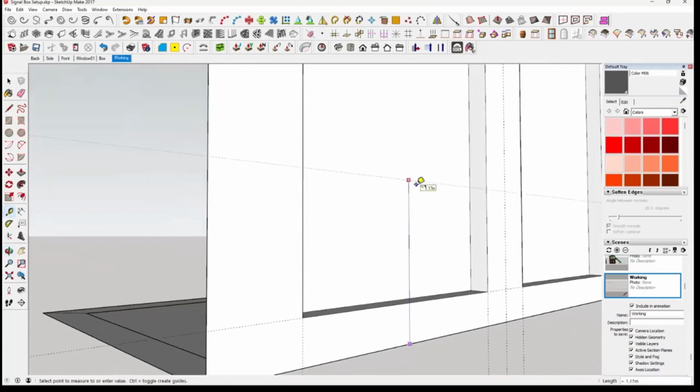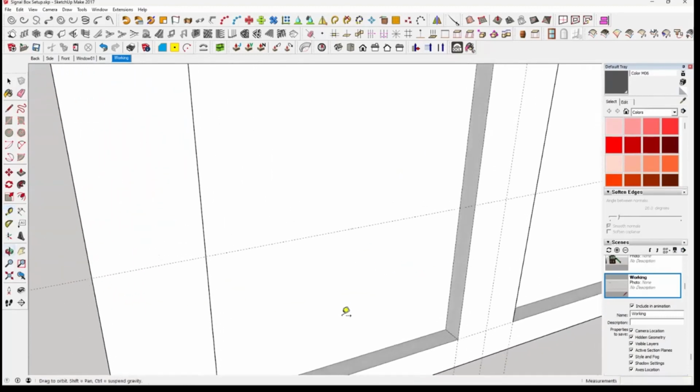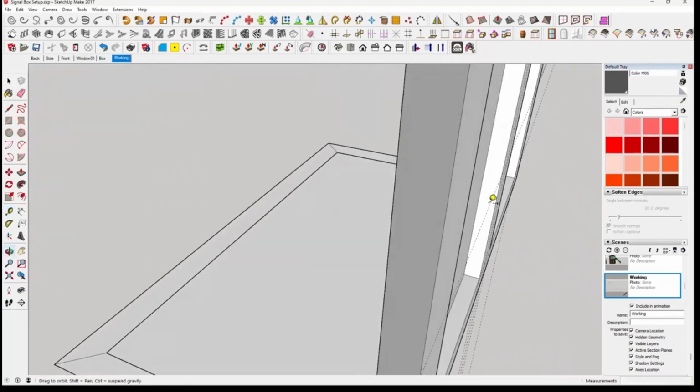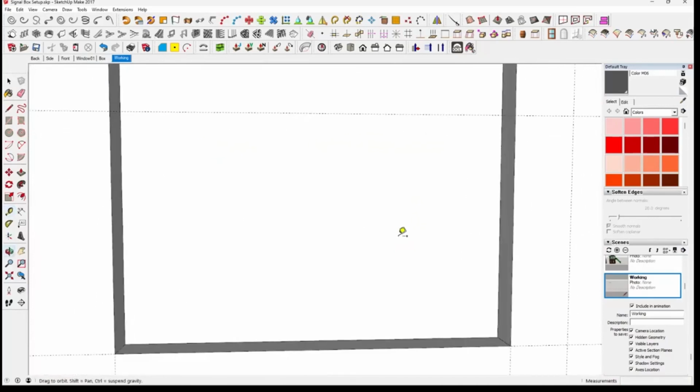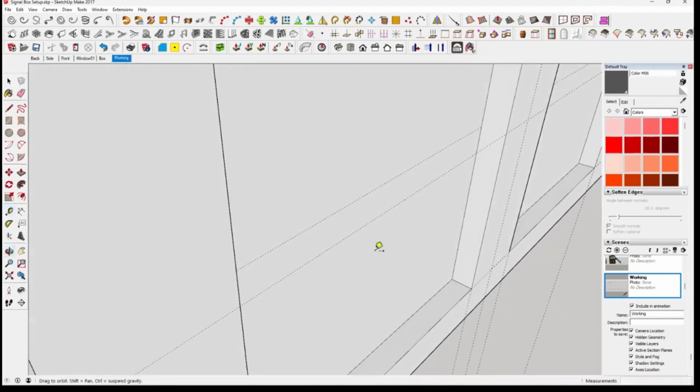We do it to 1.5. It's going to be on the front edge, so we can't actually, if you see there, we're lined off the edge there. But what we can do is reference the back now. So if we click on the back wall and go on the Z, so it's the up arrow, and then we go up and we reference off that line we just made till it changes. And there we go, we've referenced off this front line onto the back.